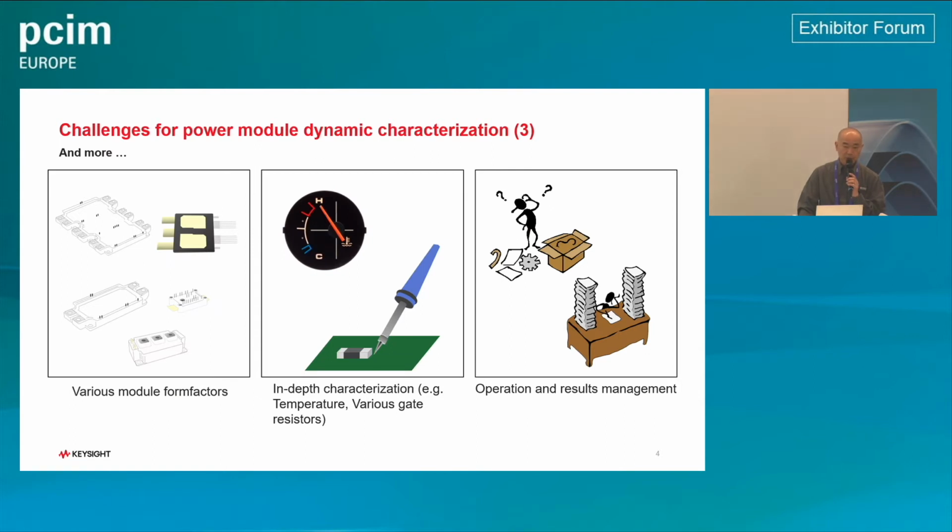And there are more challenges. There are varieties of power modules with different form factors, as shown on the left-hand side of the slide. And you need to have a nicely created interface board or something which has the minimum parasitics, which is not so easy to make.